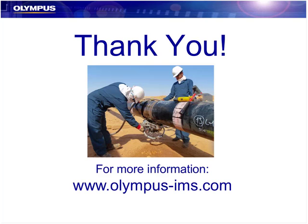How does the technique accommodate pipe thickness variation? I think this was probably asked before going over that slide. So basically there is some adaptation, especially for seamless pipe. We allow multiple setups that fit a range, and then we take a measurement and apply the most suitable setup. They are all acquired at once, and we use that criteria or that setup information to do the analysis.